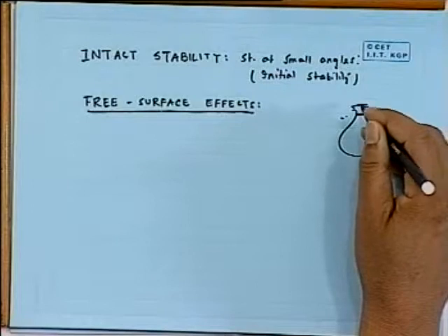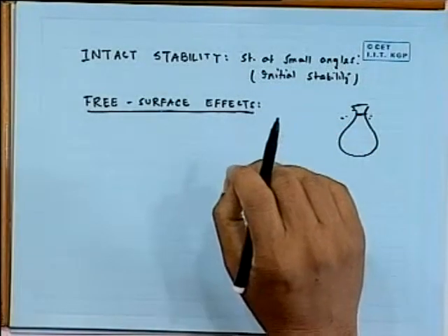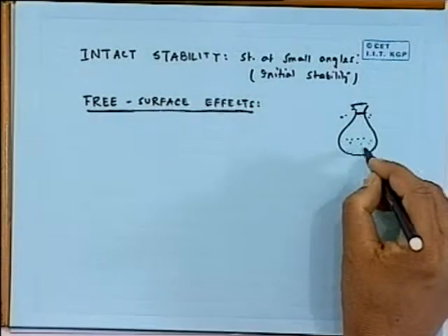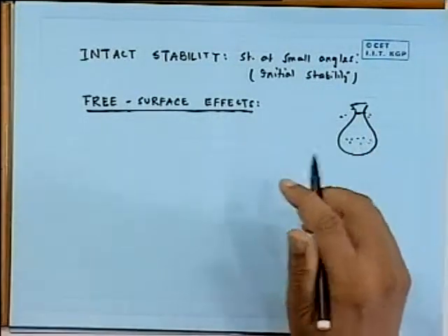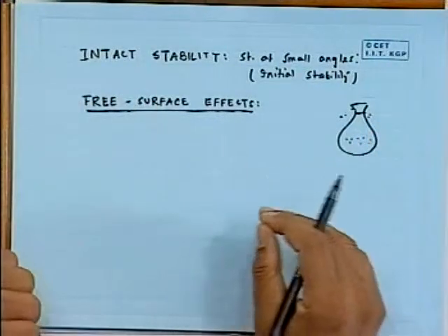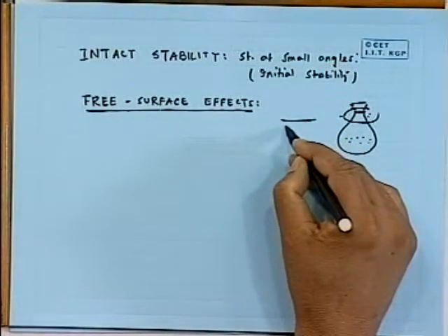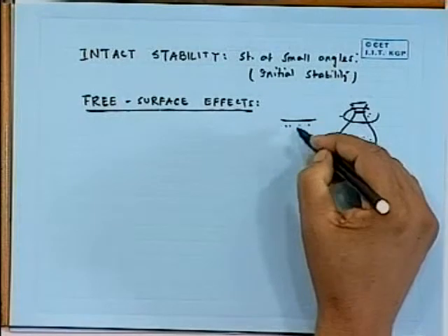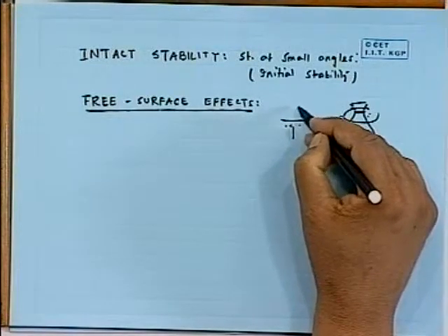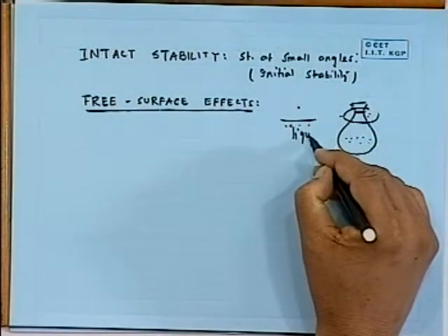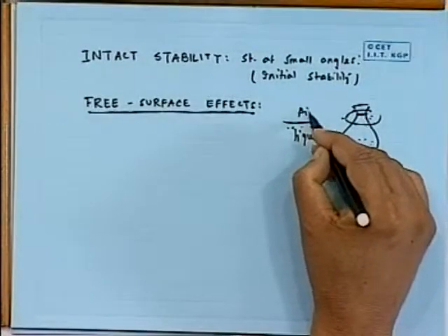When you cannot do that, you will see the milkmen actually put some kind of hay inside. Again, that is for damping the liquid, so that the milk doesn't spill over. The entire concept of all this is that you want to reduce the free surface. Free surface here means the surface where the liquid is here and air is here. This is an interface of liquid and air.